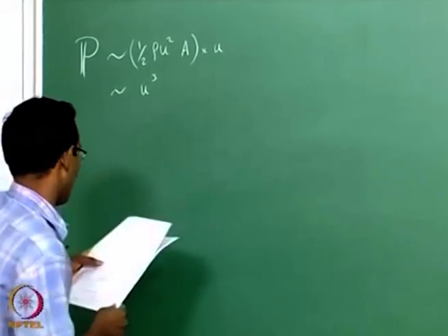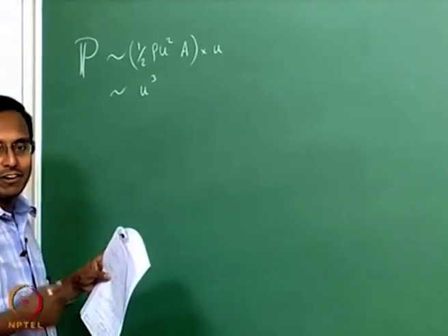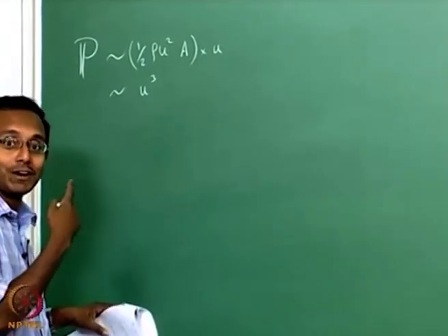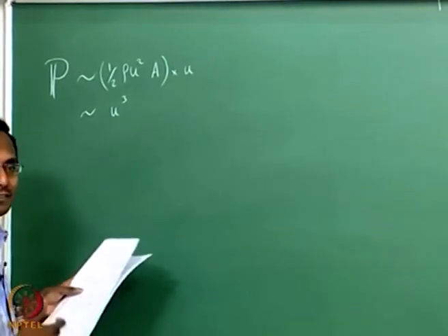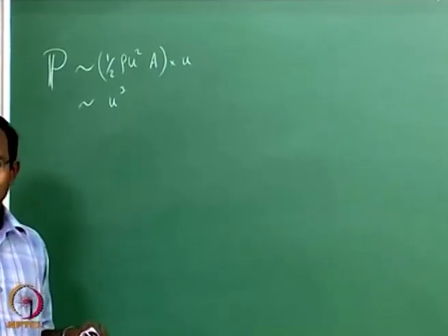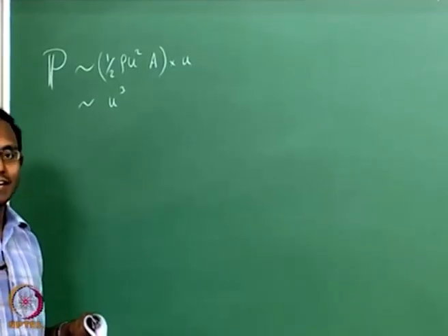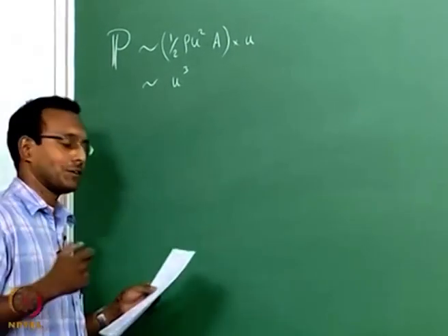That is the main option. If I think about continuous facilities, I have to keep on giving it continuously at this power rate, which is not going to be easy to deliver, this much energy per second. That is too high. So typically we will see only intermittent high speed wind tunnels. We do not see continuous wind tunnels ever.